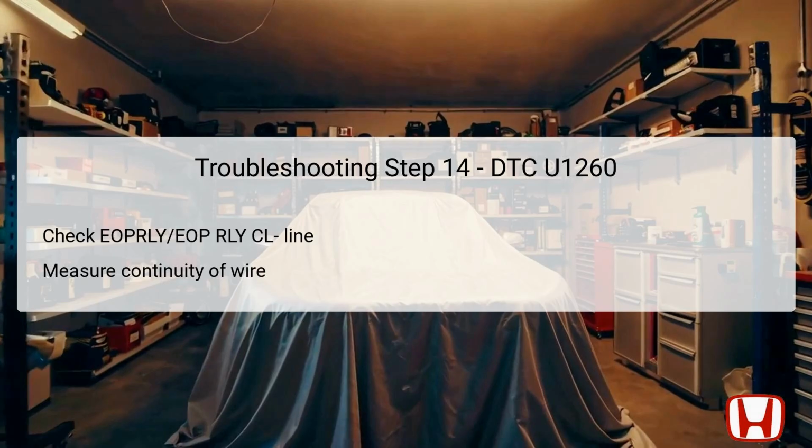Testing for continuity is essential to ensure that the wire is intact and the relay can be properly engaged. If continuity is confirmed, it indicates that the wiring is functioning correctly, allowing the relay to operate smoothly. On the other hand, if you find no continuity, it suggests an open circuit requiring repairs.